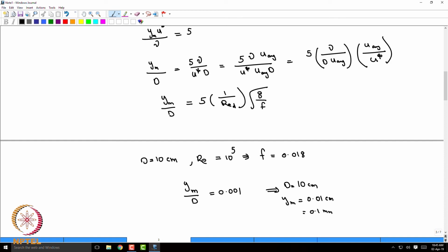So that means if there is a flow that's happening on a very rough surface, that flow is going to get affected by the roughness. That flow is not going to be smooth. Actually, another way of saying it is that the wall layer itself gets disrupted because of the roughness. The roughness that you might not have imagined would play a role actually will destroy your wall layer and will affect the entire flow field. Therefore, pipe roughness affects turbulent flow. That's the takeaway point. Is that clear?